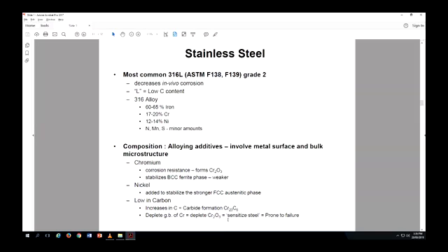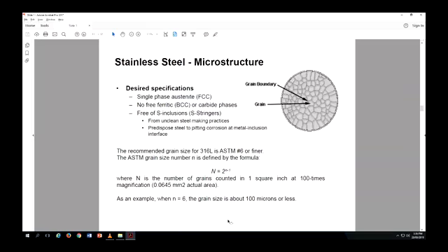carbide, if you look at it under the microscope, you will see a lot of grains forming. The boundaries are very important because these are areas of stress concentration, weaker areas compared to the inside of the crystal. Sometimes carbides can cause a lot of depletion of the chromium from the boundaries, and then it will give you a weaker material. So this is why different compositions are important in the alloy.